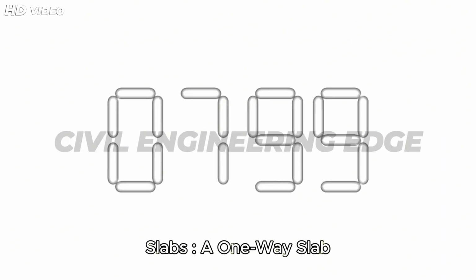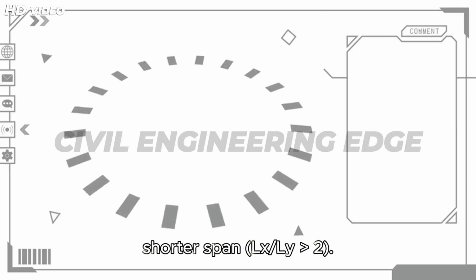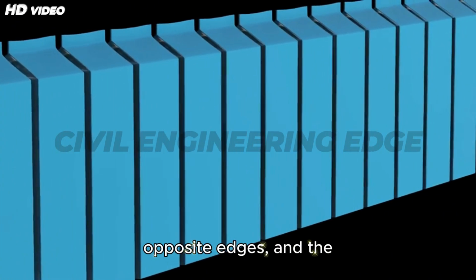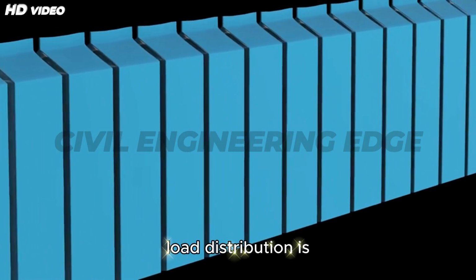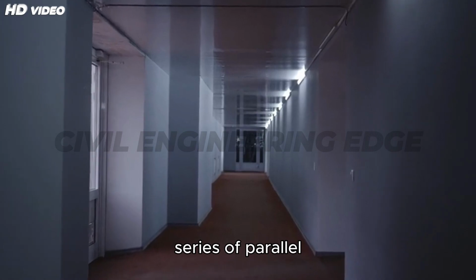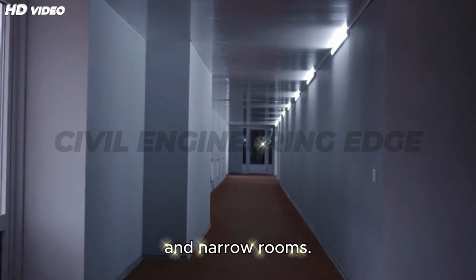Design of one-way slabs. A one-way slab is a slab that bends in only one direction, typically when the longer span is more than twice the shorter span, Ly/Lx greater than 2. These slabs are supported on two opposite edges, and the load distribution is along the shorter direction. They behave like a series of parallel beams and are common in corridors, footpaths, and narrow rooms.